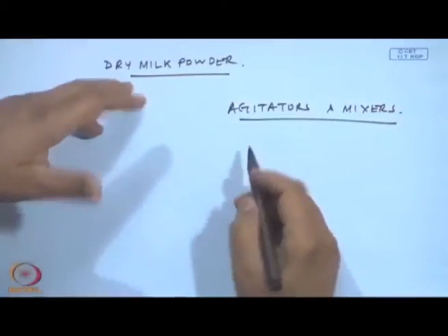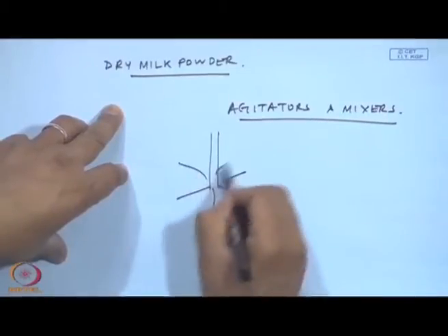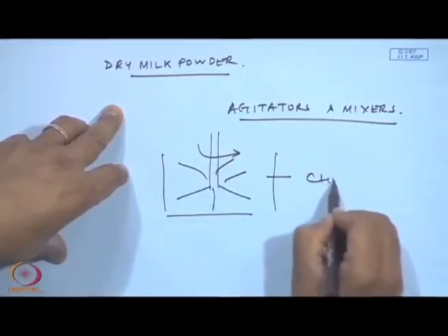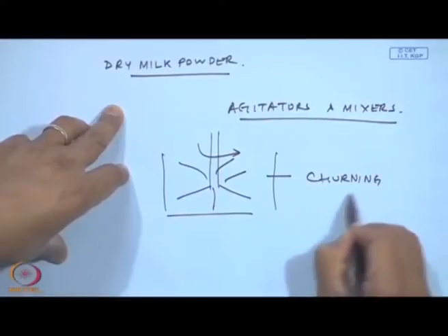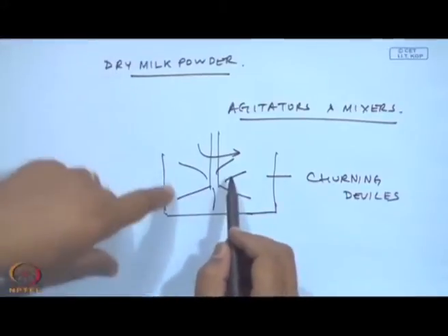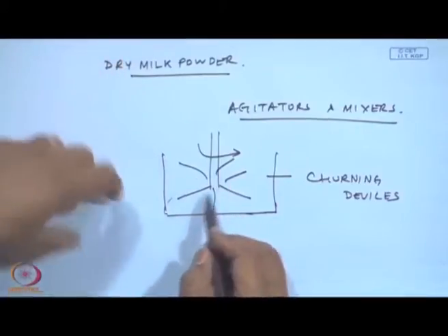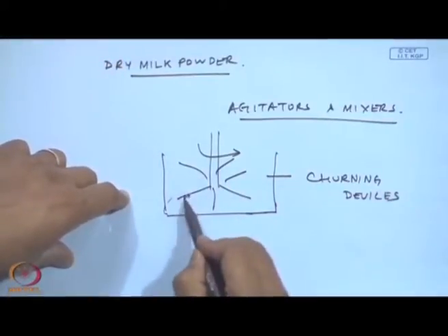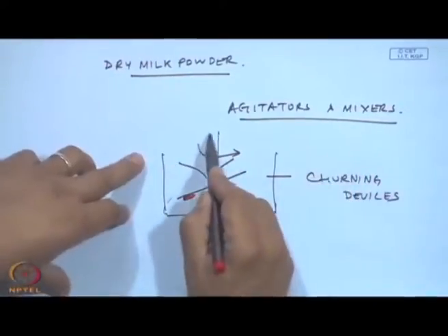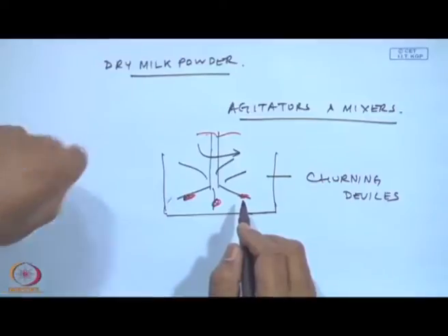Okay. Agitators and mixers are nothing but high speed churning devices in a tank. Again the same thing: if I feed in certain material which is susceptible to moisture and becomes sticky, it will stick to the blades, and because this is rotating, it creates unbalance, and finally some fine day this thing fails, because of excessive fatigue loading.